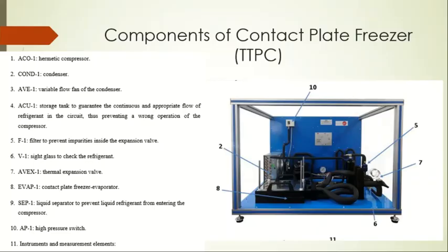So definitely at certain parts it is required to install a filter for that refrigerant. Okay, so that ensures there is no choking up on various parts of this contact plate freezer. So it's just for prevention basis.